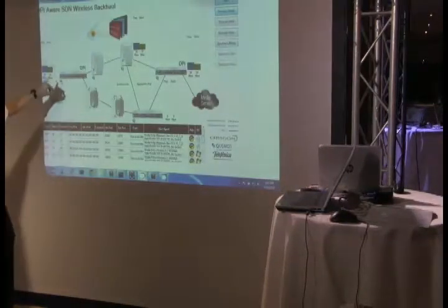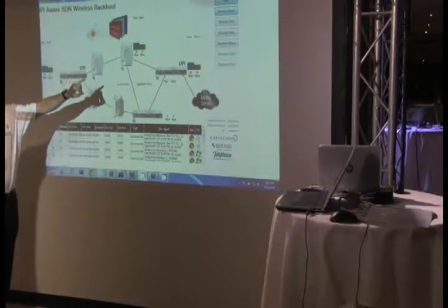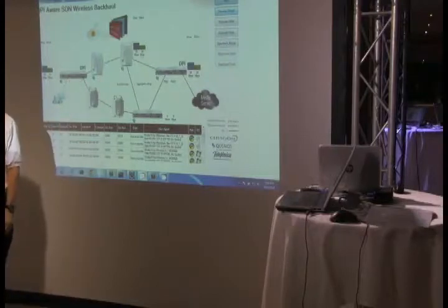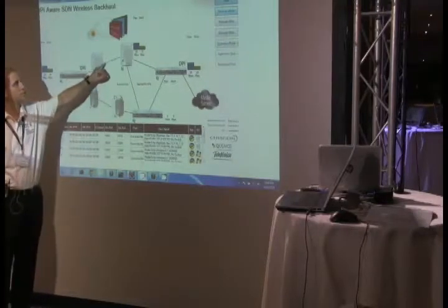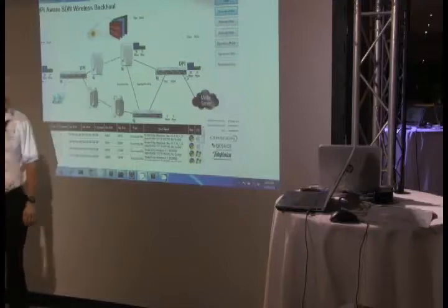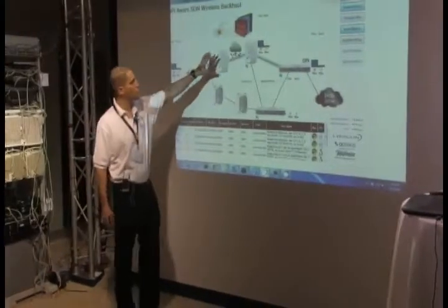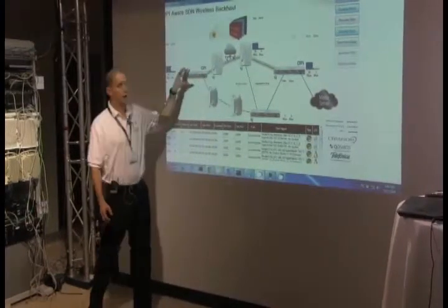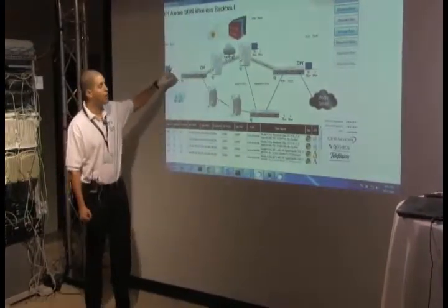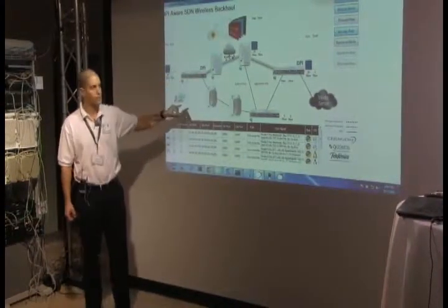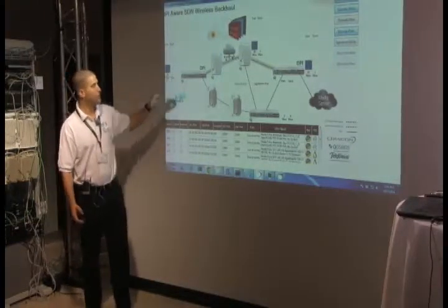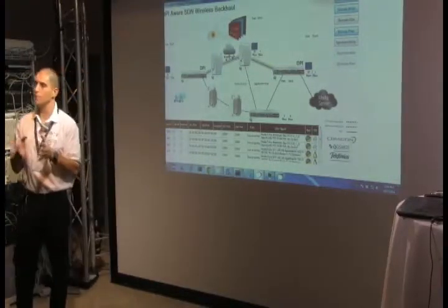So again, focus on the green traffic, and what we're going to do now is simulate some rain on this microwave link. Now, when you've got rain on a microwave link, which is this situation, the capacity shrinks, and what happens is that all the green traffic is being dropped, because the blue traffic has a lot higher priority and there's simply no more space.